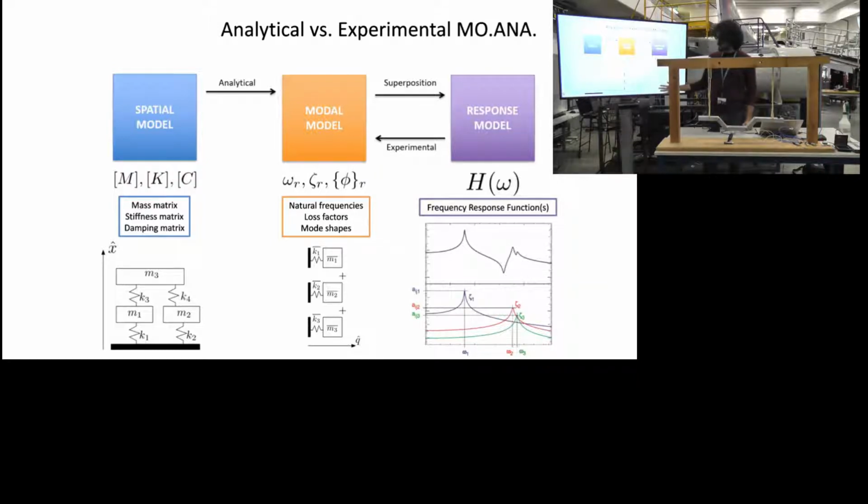Now, what I have here at the bottom is the effect of superposition I was talking about. We have this mode 1. This is a single degree of freedom system vibrating, and this corresponds to the modal mass 1. This red one corresponds to the modal mass 2, and this green one to the modal mass 3. As you can see, it's very easy. By just summing the contribution of these three individual modes, these three individual masses, you'll find what happens to the physical mass.